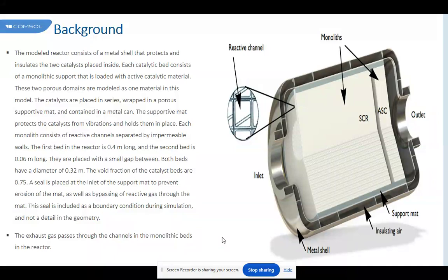It should be pointed out that there have been several efforts at improving the fluid distribution inside a catalytic converter by adding diffuser elements, changing the inlet cone, and similar solutions. But using an optimized combination of cell densities, washcoat loading, and so on has not been explored extensively yet. The temperature distribution was also analyzed. According to the results in this simulation, the temperature fields of the four cases are similar.